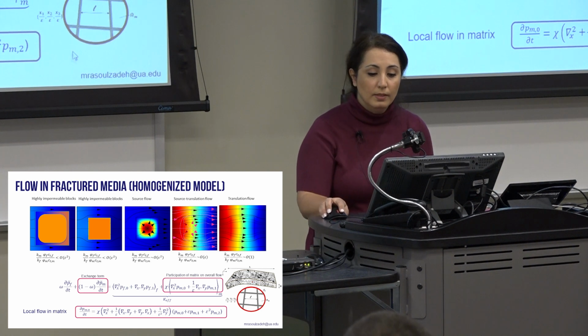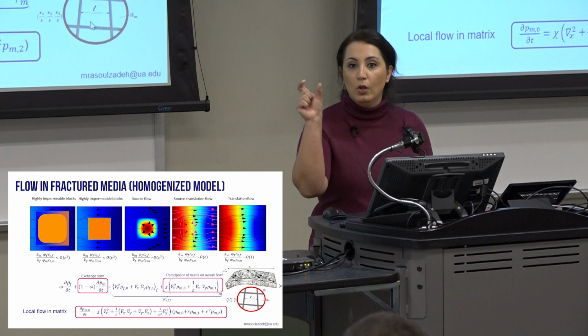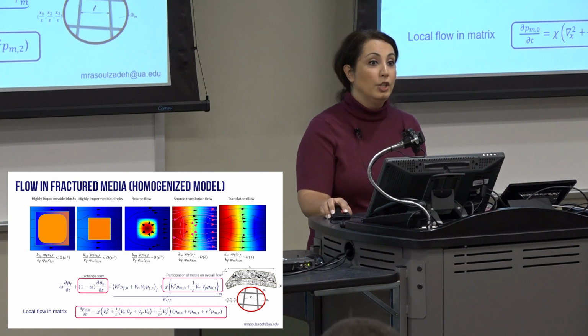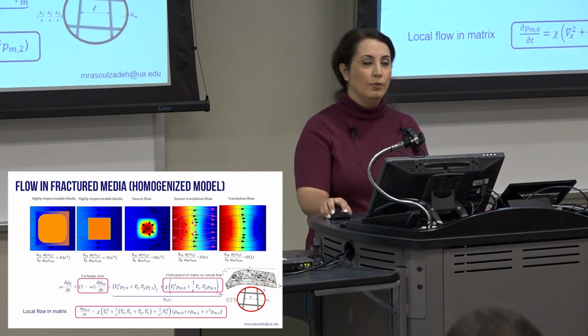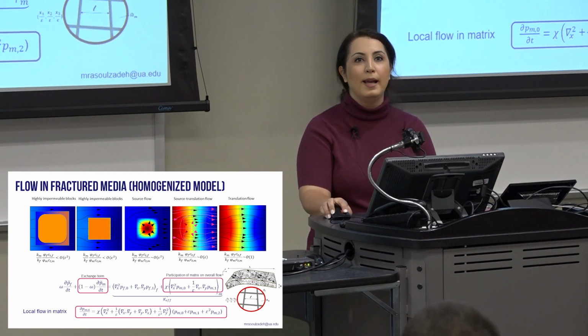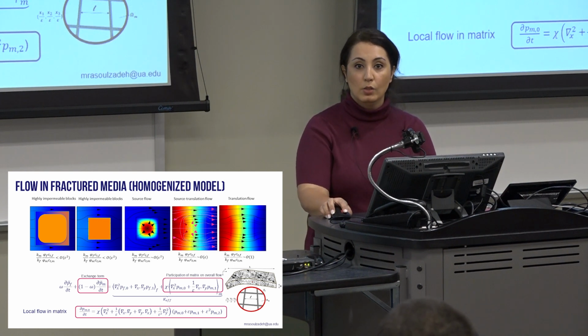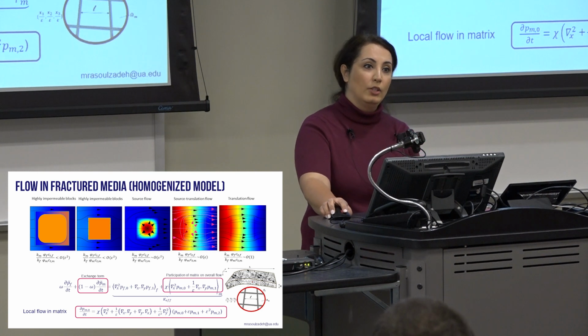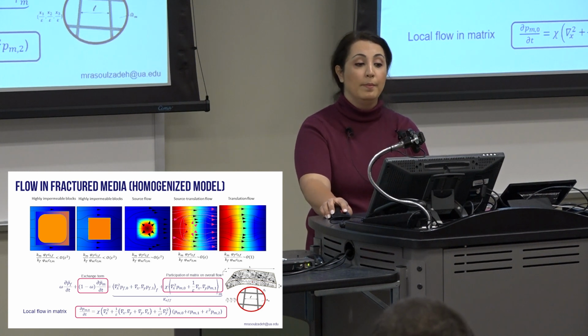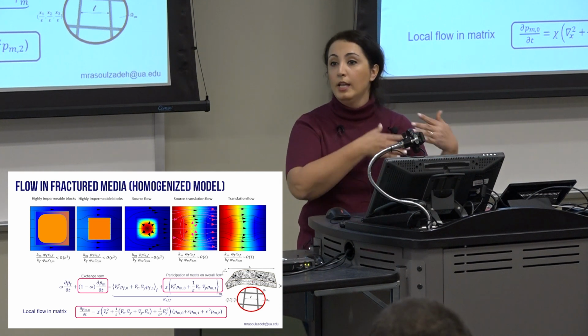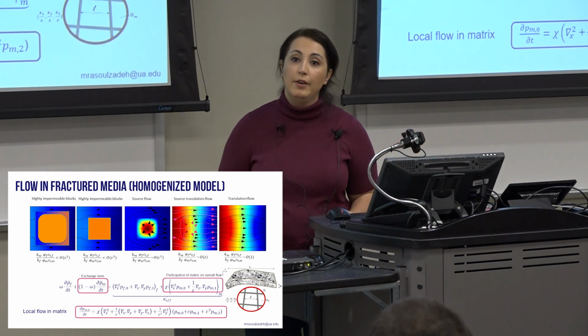So this is going to be my small parameter, how small each cell of inhomogeneity is. If the ratio of matrix permeability to fracture permeability is of order of magnitude higher than epsilon squared, that means I have a very low permeable matrix, and matrix will be completely excluded from the domain. It's just fractures that carry the fluid.